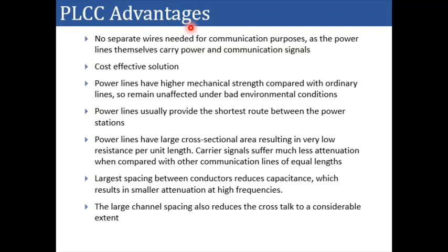What are the advantages of PLCC? The biggest advantage is that there is no separate wires needed for communication purposes because the power lines themselves are being utilized to carry power as well as communication signals. It is a cost-effective solution because you need not lay a separate line for communication purpose. Power lines have higher mechanical strength, that's why they can withstand the harsh environmental condition and they will get unaffected in terms of data communication.